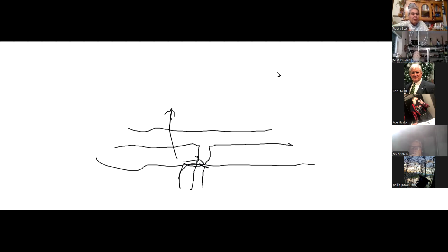No, half wave. It's about 36 inches. 36 or 38. Yeah, 39 inches is a half, and a quarter wave would be 19 inches. Yep, I just measured. It's 19 inches.